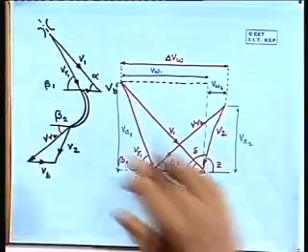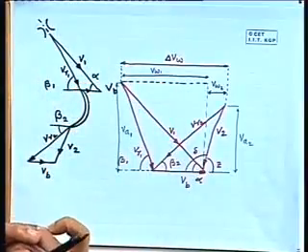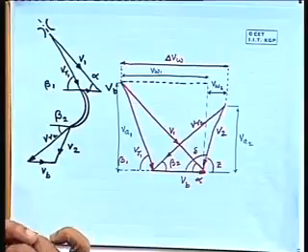It will be very slanted then, and then the blade passage will be very obscured. We cannot do it. There are some limitations. So, generally this angle is kept 12 degree, 14 degree like that. We generally do not go to a smaller angle than 12 degree or 14 degree, 16 degree like this.